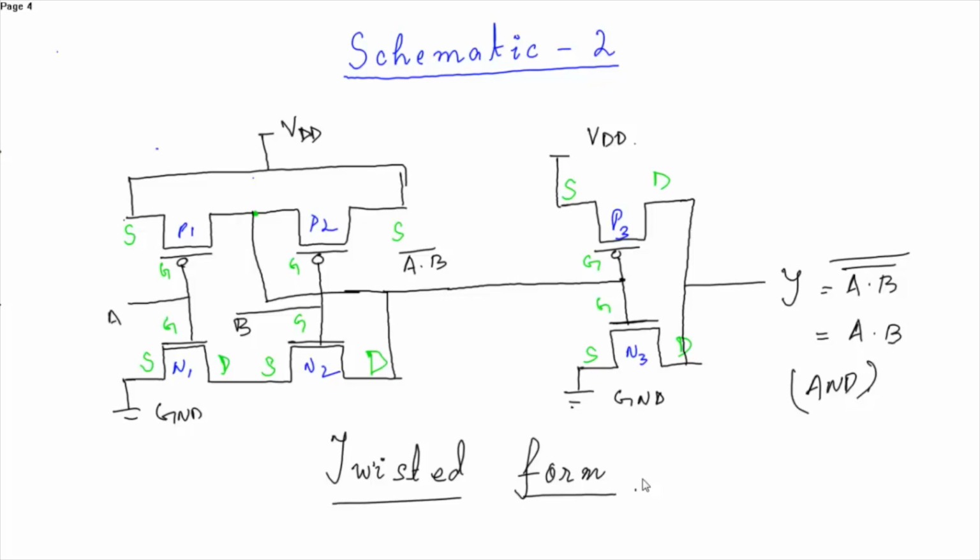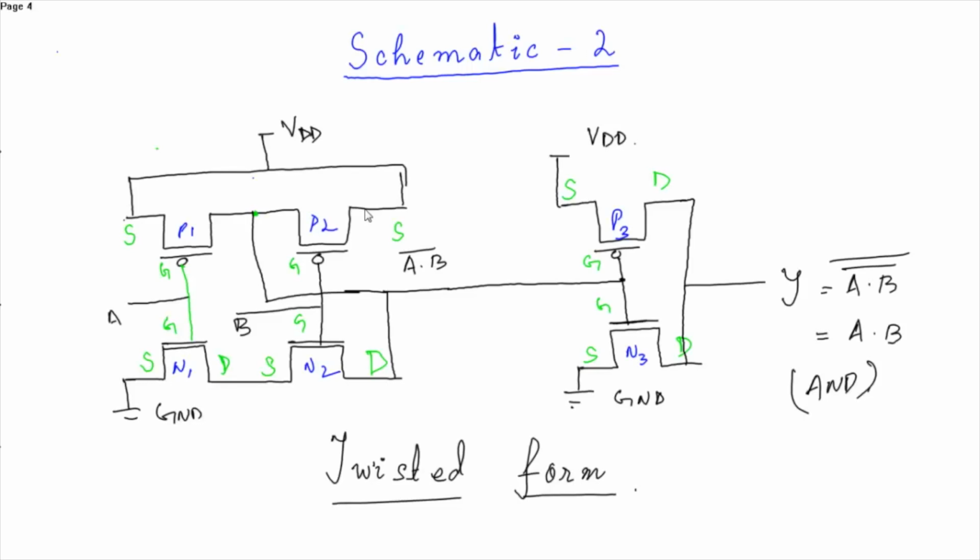Let's go to the previous page. We have to keep in mind to place all the source drain with metal layer and the gate with polysilicon layer. We all know about this, and then we have to place the corresponding contacts.